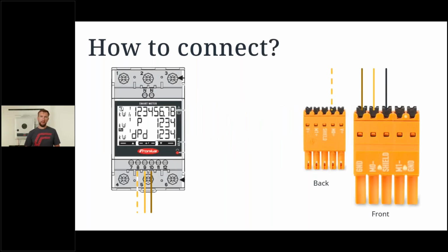So how do we connect the ends? There are several ways that you could connect a Modbus line. Now, as it's an RS-485, you can use a standard Ethernet plug at one end. It's the same topology. We also have screw terminals where we can clamp down on the cables.